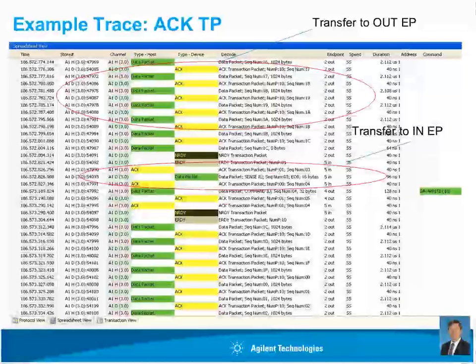So in this link here, we're looking at one communication, data going out from the host to the device, and we can see it's address 1, endpoint 2, so there's one pipe, and then the one in the middle is probably the information we're looking for, something that's hidden in the middle of a large transaction of data in on endpoint 5. We can also see that there was another endpoint involved with data flowing out and across. So there's different pieces of information you need to correlate to find your operations and see the timing of events, of when the device is not ready and how long it takes the device to respond when it's ready to receive more information.